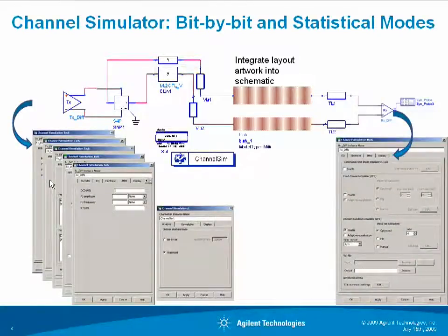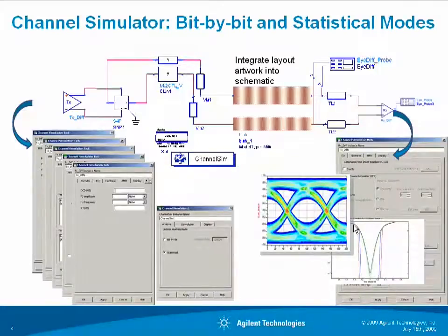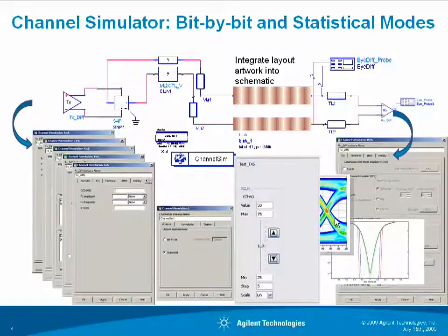Likewise, the receiver is specific to signal integrity, and it lets you set the equalization and so on, including adaptive equalization like decision feedback equalizers. A new custom iProbe component works with both the channel simulator shown here and the traditional SPICE-like transient convolution simulator. You can drive the simulator manually or from the tuning, optimization or batch mode controllers.